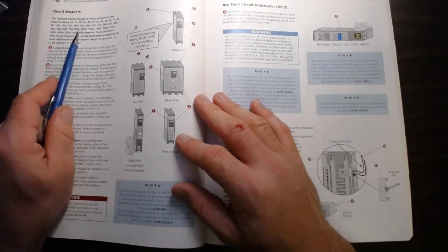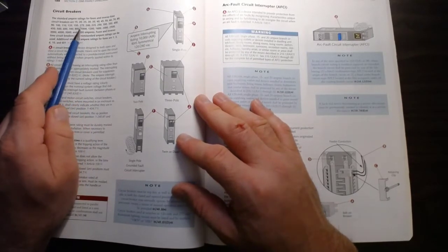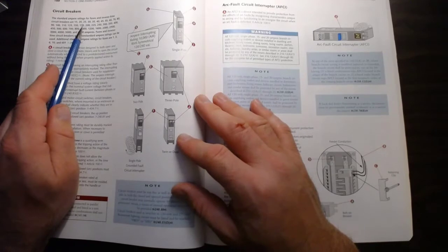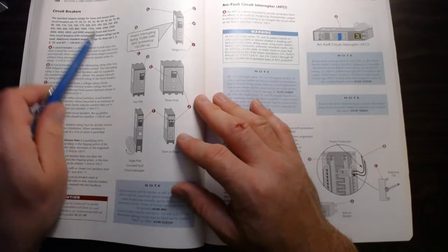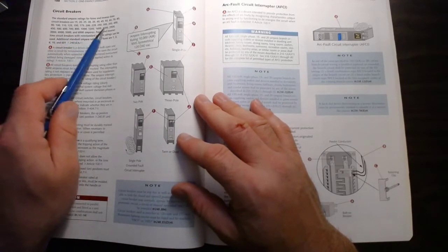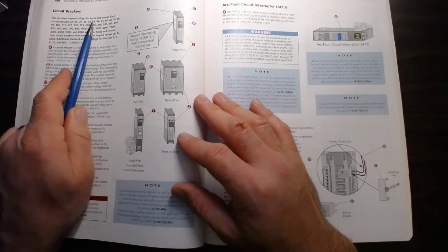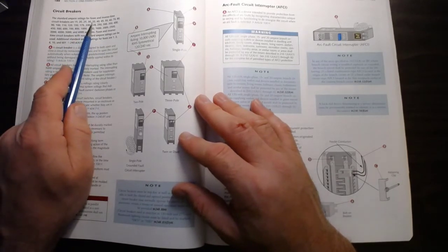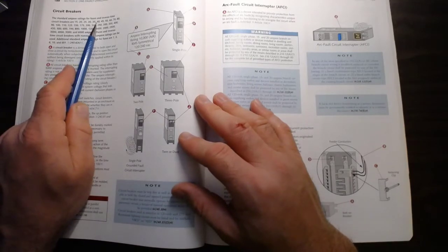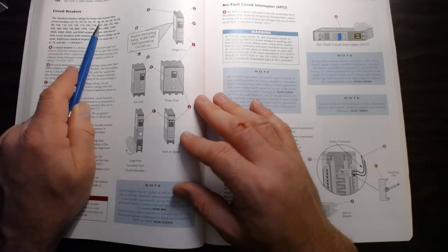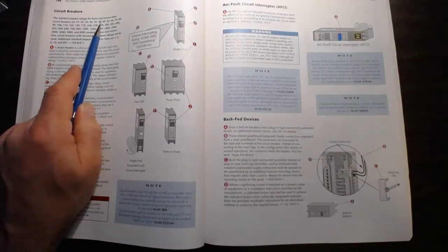Now, when we go to your project towards the end and you need to size your circuit breakers, you need to come back to 240.6 to see what's my circuit breaker size. Let's say that you sized it at 32 amps. It needs 32 amps to run your equipment. Well, you can go for a 35 amp breaker. That's going to be the next closest, but that would be a special order. And maybe need to go up to a 40 amp breaker because you can get those easily.